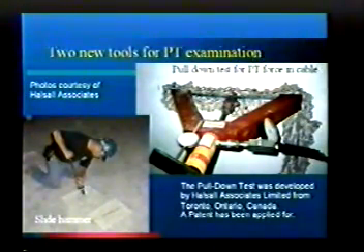This slide is courtesy of Halsall, the people that provide this. If we pull on the cable, if I can find it, grab it, and pull on it, I can tell you how much tension is on there. If I drive a screwdriver through the strands, if it's a multi-strand cable, I can tell you is it stressed or is it not stressed. Well, driving a screwdriver through PT cable all day long, you know, your arms get kind of tired. A slick device is called a slide hammer. We're just sliding against the screwdriver, and you can see right here, we're trying to separate the individual strands. So this is a time saver and a muscle saver.